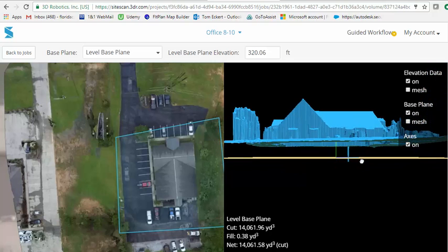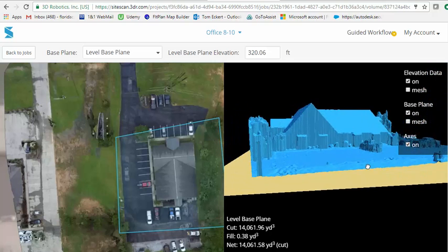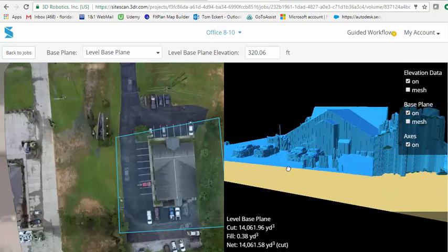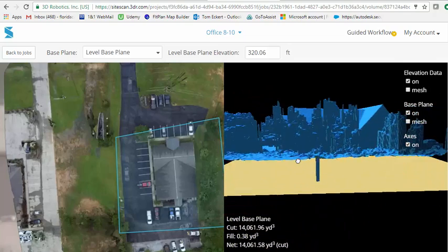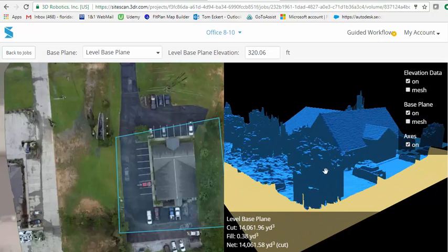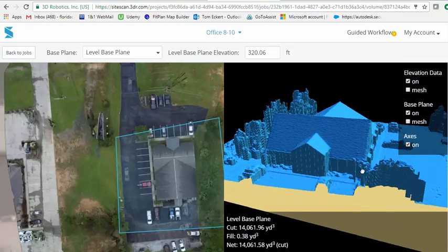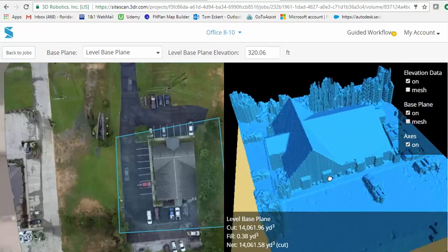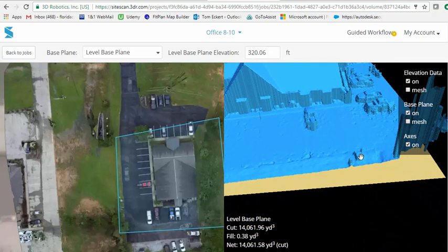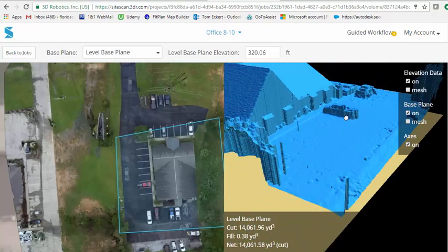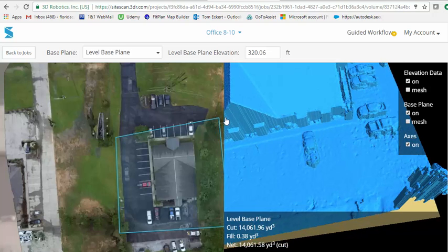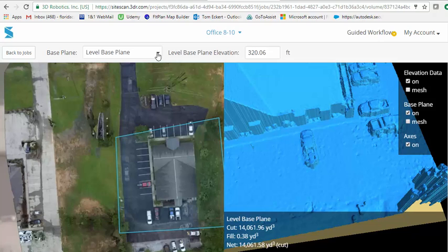Word to the wise, if you notice, it is not exactly a flat elevation. There is an aspect of GPS measuring to the ellipsoid that provides just a little bit of a skew. And in fact, in this case, it's the 1 foot. Even your parking lot, without ground control points, would have some challenges showing correctly. This is us. That's what a car looks like, by the way. Our big old truck looks like. There's the front door of the building. But we're going to go over more of that. I just wanted you to get a flavor for the different volumetrics.